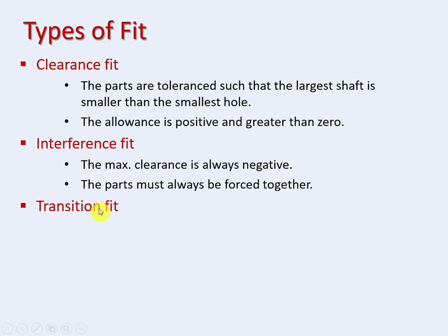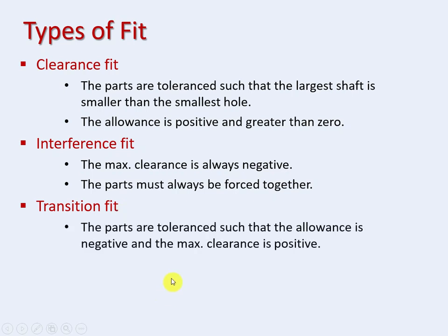The last one, the transition fit. The parts are toleranced such that the allowance is negative and the maximum clearance is positive. The parts may be loose or forced together.